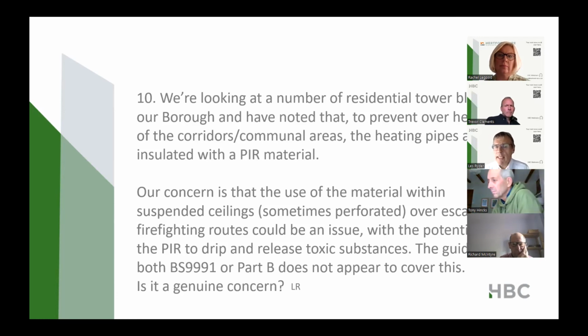Now, what PIR does do, it chars, it doesn't melt. It hasn't got a melting point. If you look in the description of PIR, it'll give you a heat of combustion, and when it comes to its melting point, there'll be a dash against it, and next to it, it says it chars, and that was proven on Grenfell. Most of the PIR and the phenolic foams was still on the building afterwards, because initially it would have combusted and then it would have charred. So as a general rule, I'm not concerned about it, but this insulation will happen.